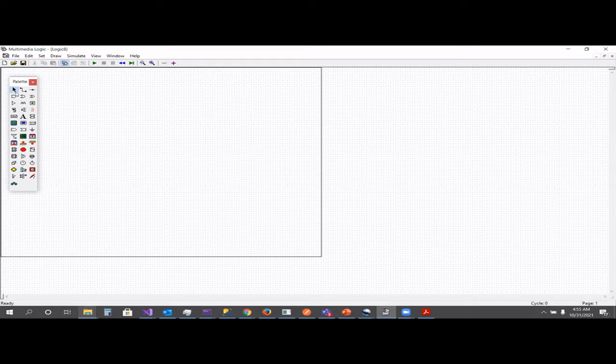Here, can you see there's something to select, like we have in Paint? And there's a wire here. I will tell how to use this practically, but this is just the introduction. Here you can see an AND gate, an OR gate. XOR, don't worry about it too much. And here you have the invert or the NOT gate. We don't have NAND and NOR gates because you can easily construct them with the basic logic gates.